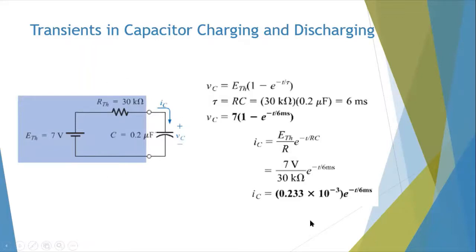So you've converted your part where you had the resistances in a cascaded configuration. You've simplified all the resistances to an RTH, and of course your E would not be the 21 volts now, but an ETH, because that's what would appear across your capacitor and the resistor. So this is where Thevenin's theorem becomes handy. You can simplify the circuit into an ETH and an RTH. Once you get it in that format, same equations we've seen for VC, for tau, and so on.